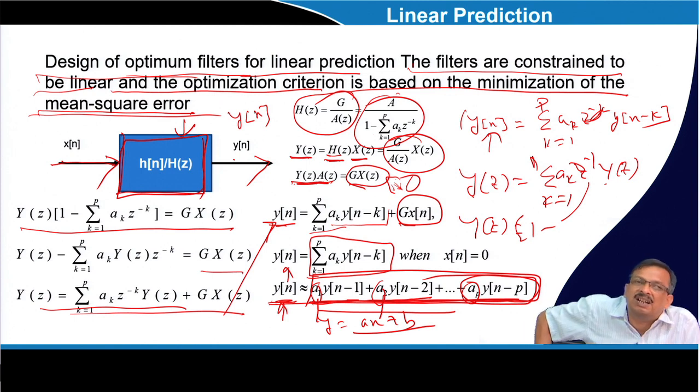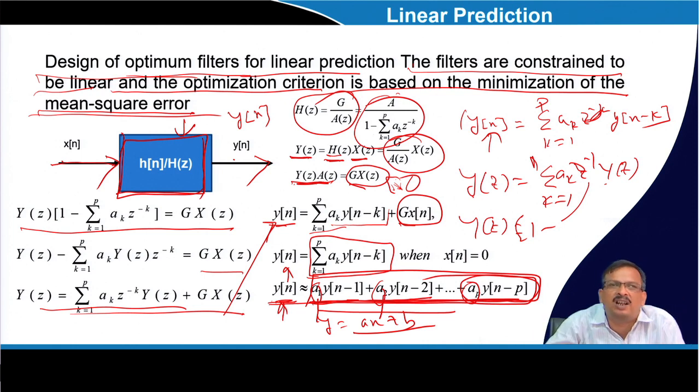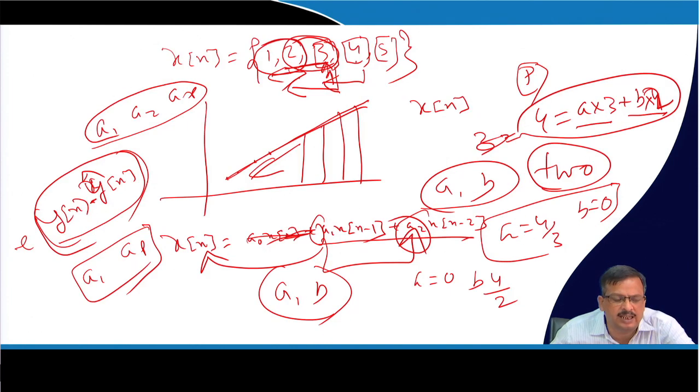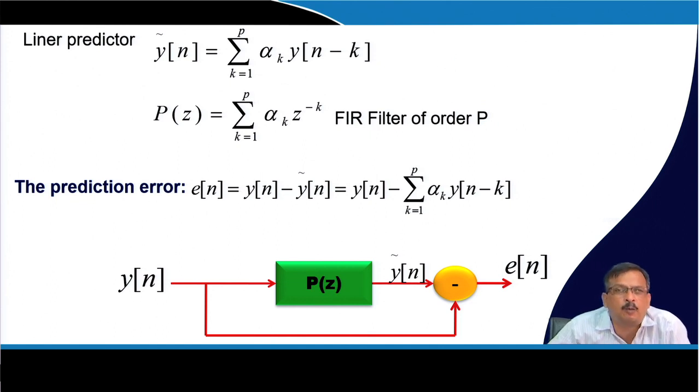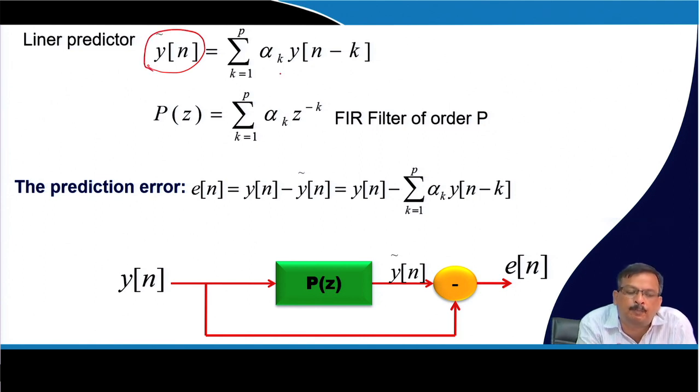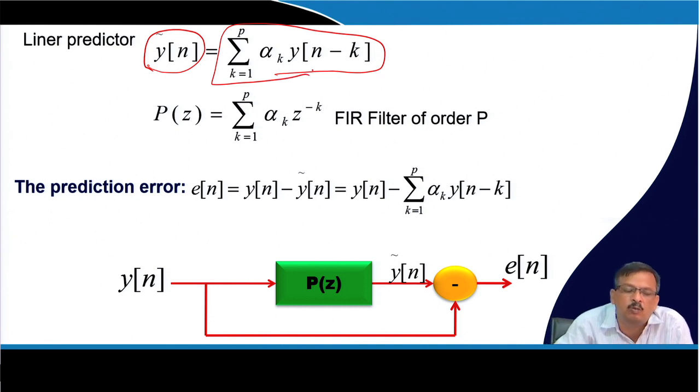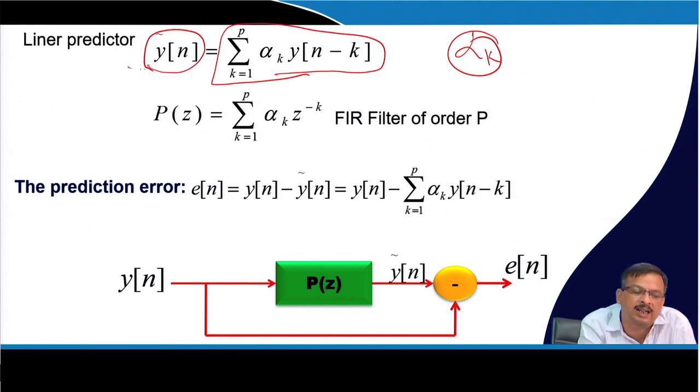That is called modeling. So, when I say auto-regressive modeling, I use it for linear prediction. Okay. So, in case of linear prediction, what is the problem? The problem statement is, I am estimating the present sample from the previous p number of samples, a linear combination of p number of samples with a multiplication coefficient alpha k. So, alpha k is my prediction coefficient, and with a linear combination of the previous output, I get the present output.